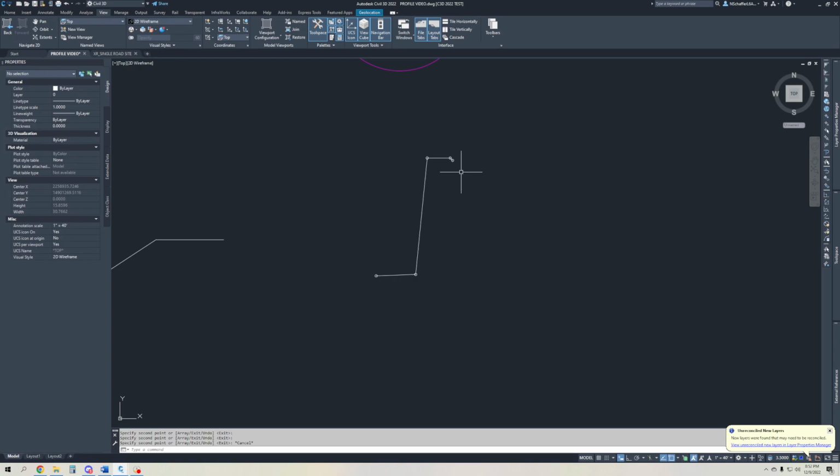So when you're going through and doing feature line grading, you sometimes have to get a little creative and think about how the section would look and where you would want to place your feature lines, and where you would want those folds to be in your piece of paper that is your finished grade surface. So with that being said, those were my couple quick examples and ideas on what you would do for feature line grading. That's all I got for this video.